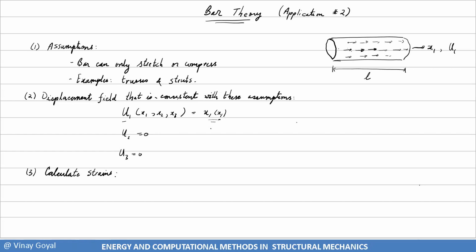In this theory, I'm going to use the infinitesimal strains. I could use the undeformed body strains, Green Lagrange, but I'm going to just go with infinitesimal strains as it applies for many different problems. So we know that epsilon ij equals 1/2 ui comma j plus uj comma i. I challenge you right now, and you will see that epsilon 1, for example, is the derivative of u1 with respect to x1. And that's simply the derivative of small u1 with respect to x1. And to make it simpler, I'll just call it u1 prime. It just makes it simpler.